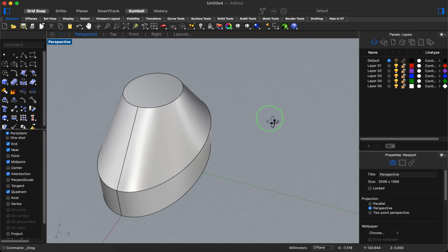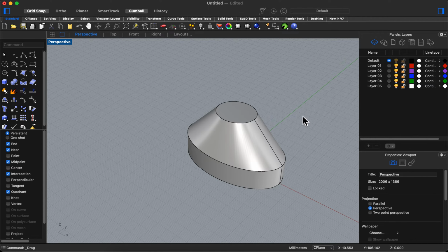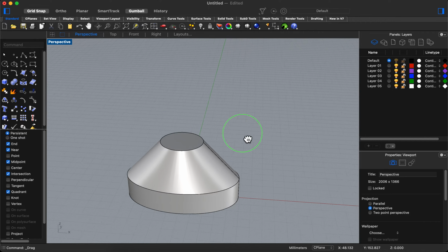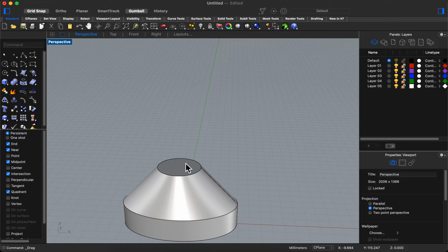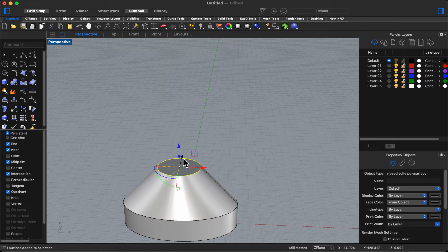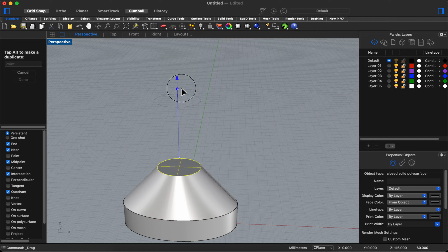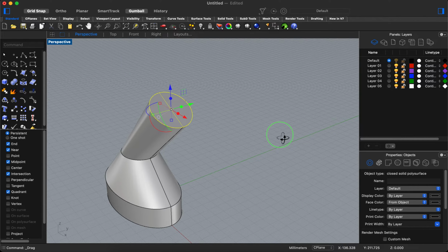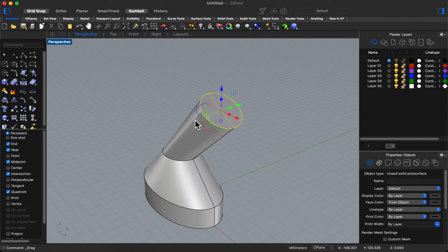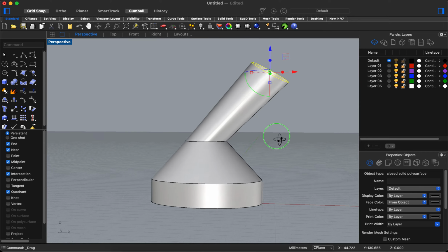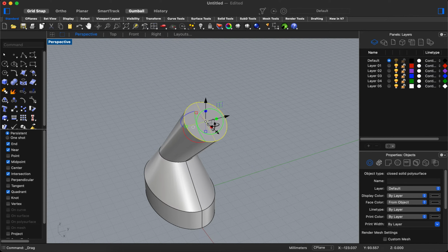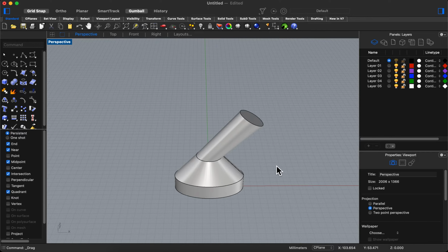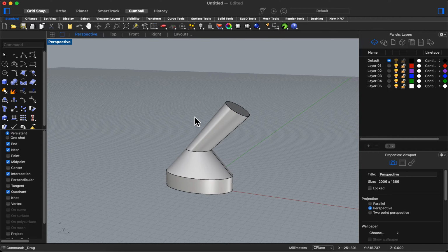Yeah, so that is how you quickly create some sort of shape to do some exploration, right? And if you are not happy with this one, or if you're happy and want to carry on, same thing. Hold on the Command Shift key, it brings it up. You can adjust the direction, you can adjust it everywhere, wherever you want. So you can actually control the surface where you want it to be. And when you are satisfied with the angle or whatever design that you want, you can just start from there. So that is how to utilize the gumball function.